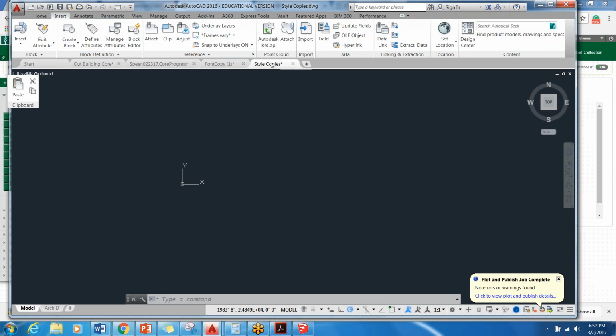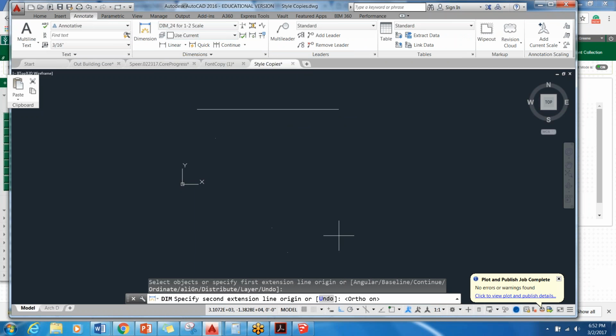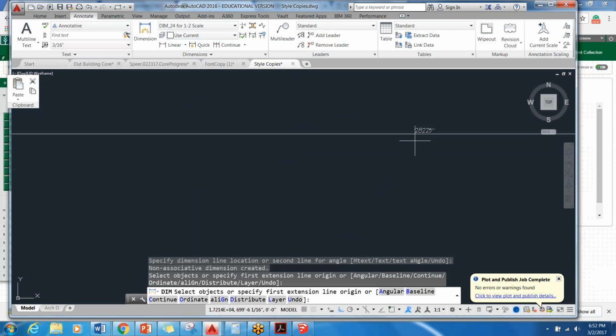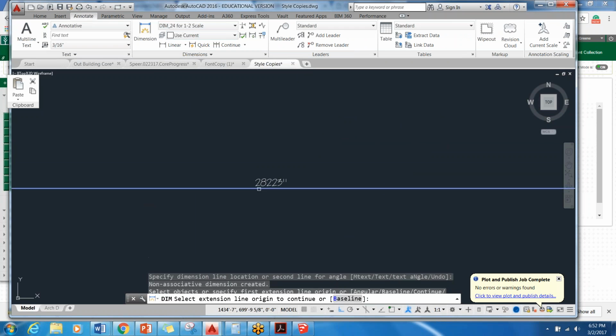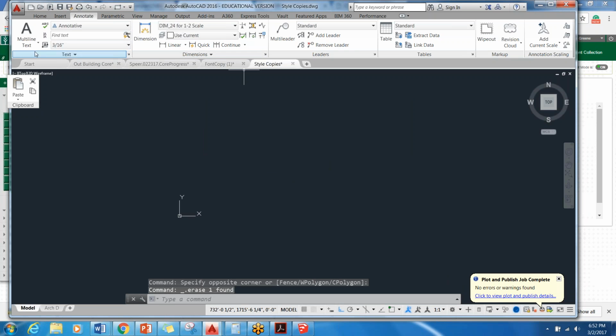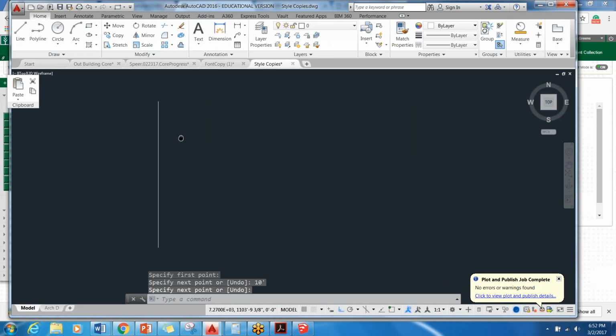Let me talk about it. I think that I made it right. So if I go to annotate and I pick the 1/2 inch scale, unless it didn't save it, and turn this guy on. Okay. So I need to give myself an idea of scale though, because right now I don't have anything for you to know how tiny or big that was. So let's do this as 10 foot. Okay, that makes more sense. I swear I adjusted that dimension style.